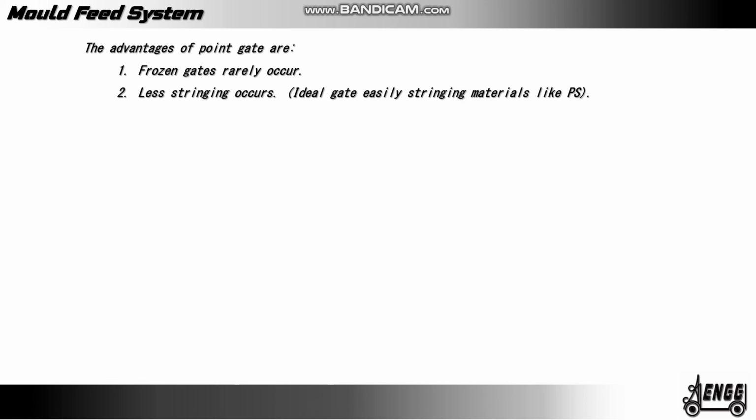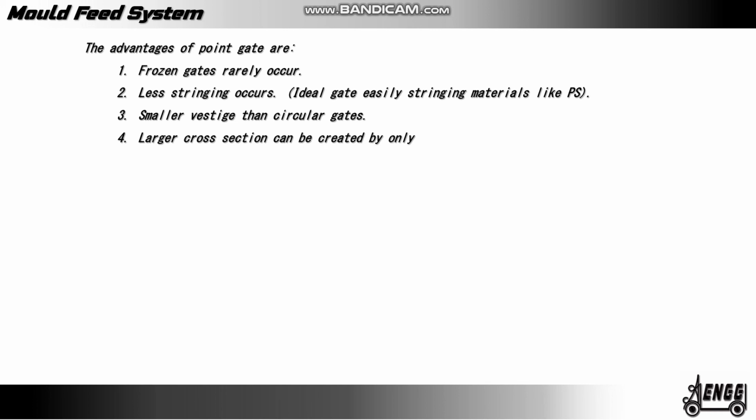The advantages of point gate are: frozen gates rarely occur, less straining occurs, ideal gate for easily straining material like PS, smaller wastage than circular gates, and a larger cross section can be created by only a little increase of the gate opening.